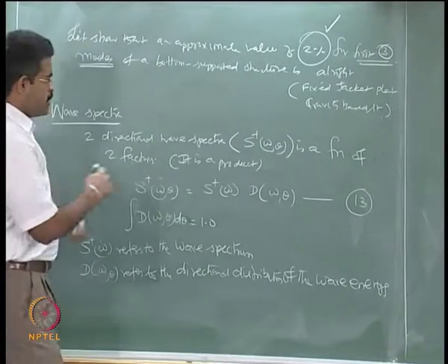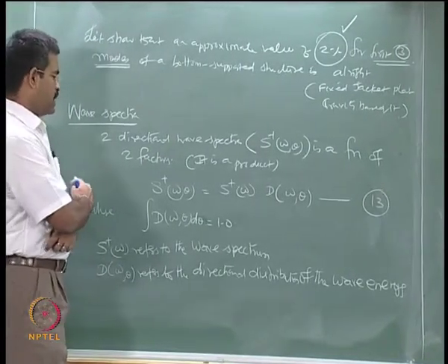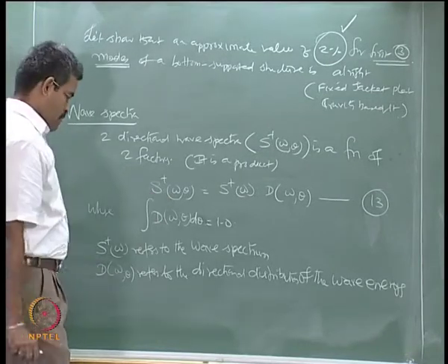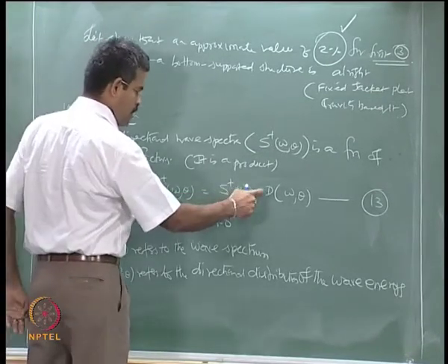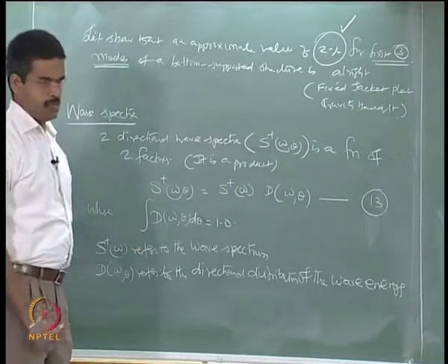This is a general combination of any spectrum which is being used in marine structures, which has a product of the wave spectrum multiplied by the directional energy distribution.